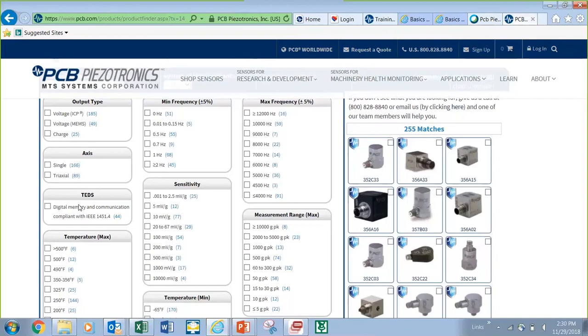That includes model number, serial number, sensitivities, calibration dates, etc. When you use a TEDS-enabled signal conditioner or TEDS-enabled data acquisition system, it will look at that EEPROM on the sensor and automatically recognize that sensor and scale that measurand based on the sensor sensitivity. So it's highly desirable in high channel counts. That way you don't have to go into each individual channel on a DAQ system to enter specific serial number sensitivities. So very convenient for a high channel count.